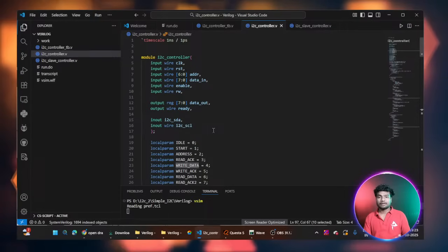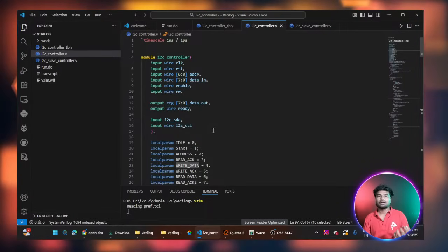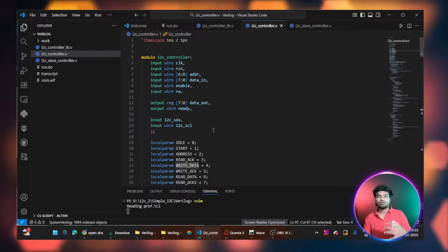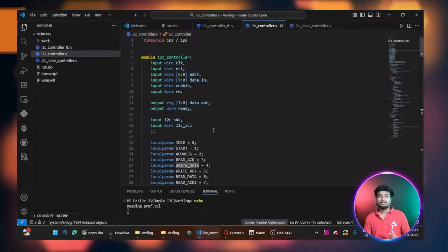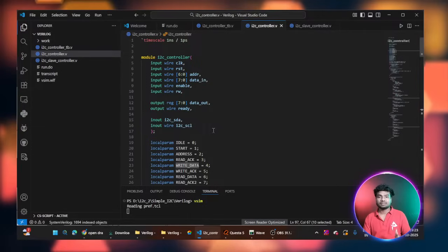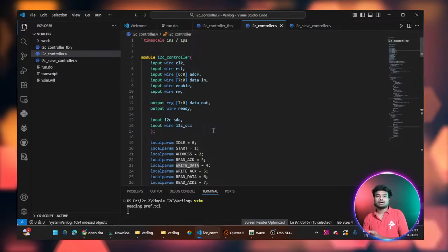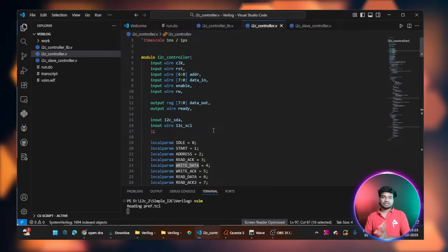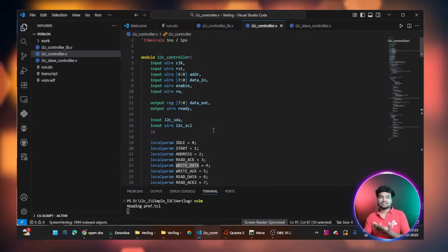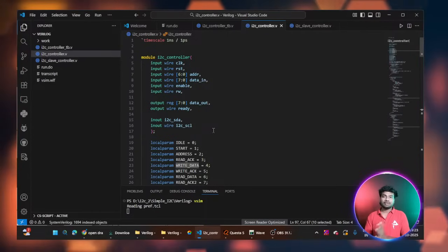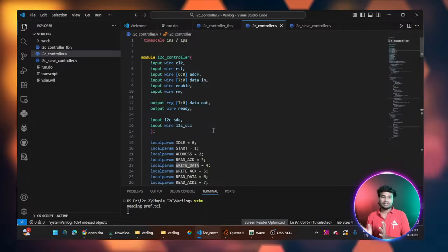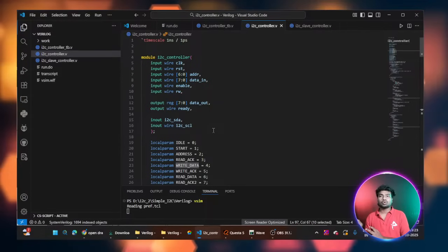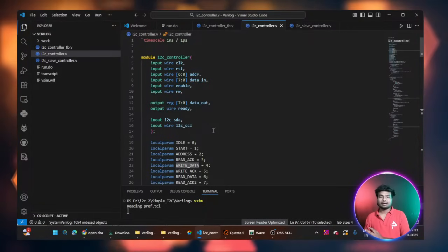We can control the open drain combination, like open drain logic, low and high. We can control these by code in the FPGA, but you can't do that in controllers like a microprocessor. Why? Because they come under ASIC chips, so you can't customize or reconfigure. If one IC is made, it is only for that particular task. You can't do anything else in an ASIC chip.